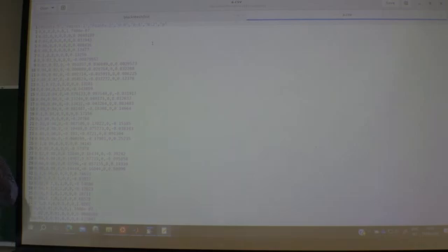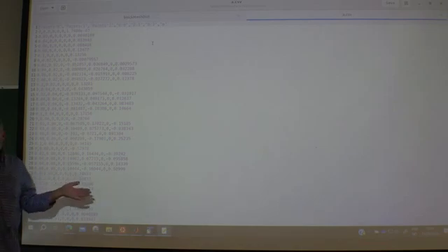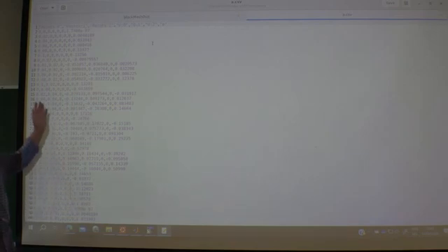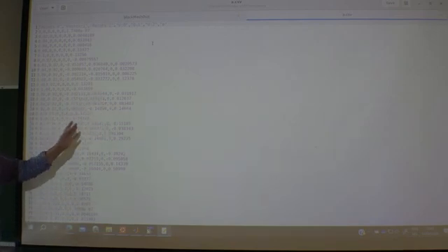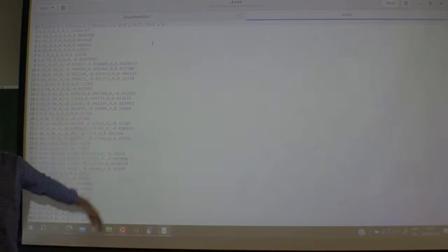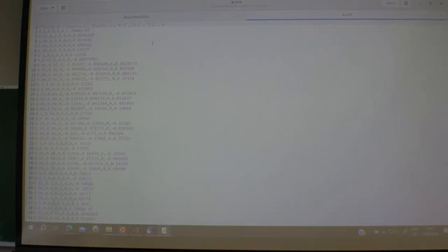That will be the velocity in the X, Y, and Z direction, and then finally the pressure. Of course, if you had a turbulent case, this one is going to be pretty long. You have K, epsilon, U, and T, Y plus, I don't know. You can have a whole bunch of numbers here. But for the laminar case, not that many.